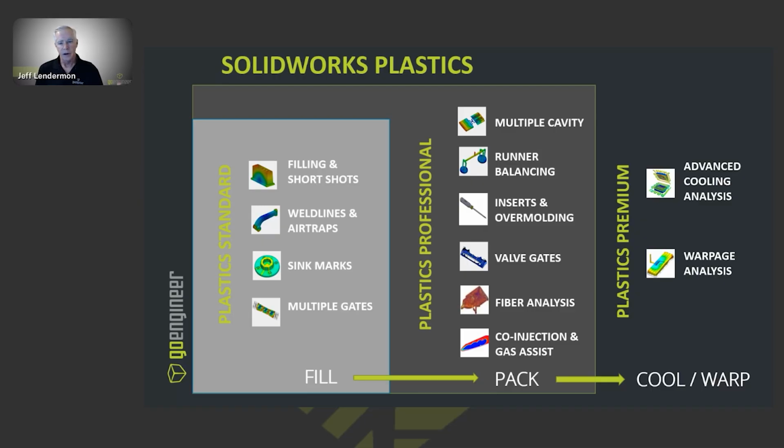Plastics Standard is just the filling phase of the injection molding process. So we have fill, pack, cool, and warp. The filling simulation is going to show us how the material melt flows through your part cavity. So this is good for part designers.